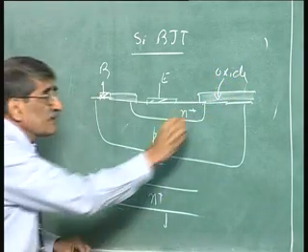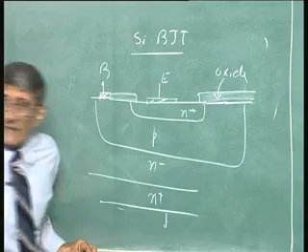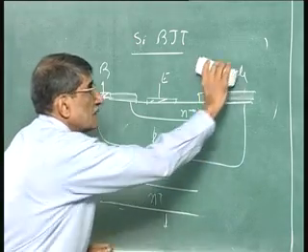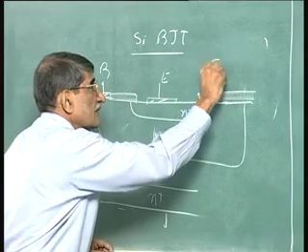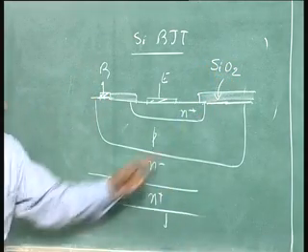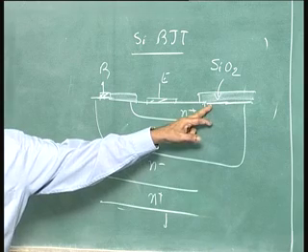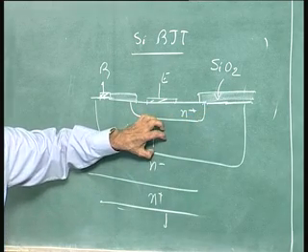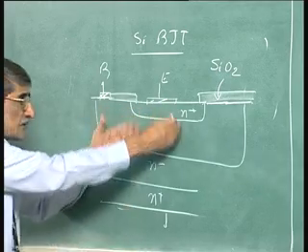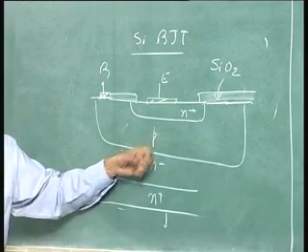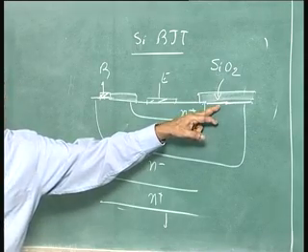So, this surface here has a protective layer of oxide. Okay. So, that is silicon dioxide, good thermal oxide. So, the recombination velocity, what we talked of last time, in the sense just like in the case of bulk, where stored charge divided by lifetime is the recombination current, okay, you have got recombination current into the surface.